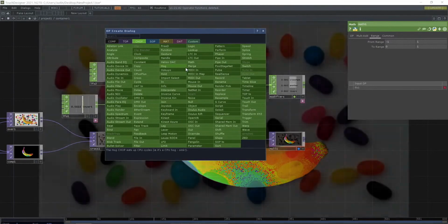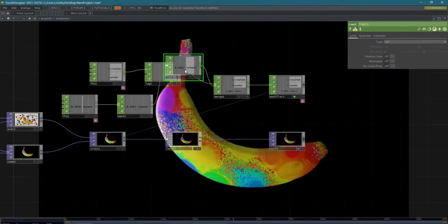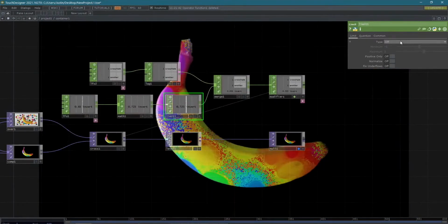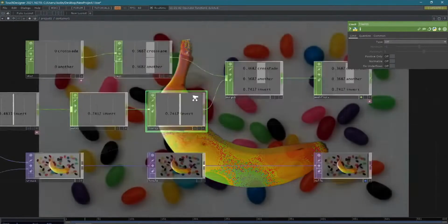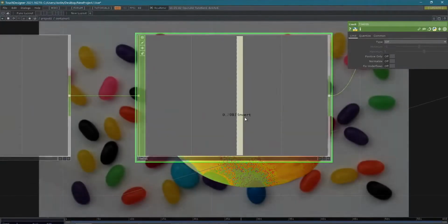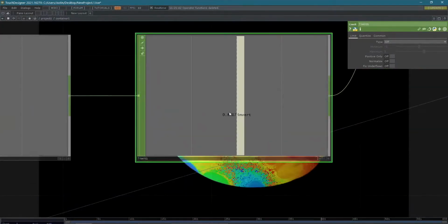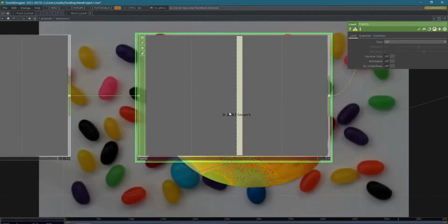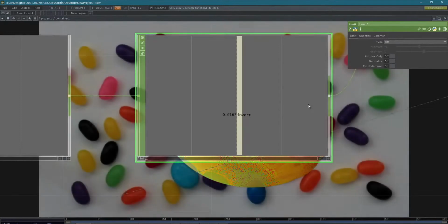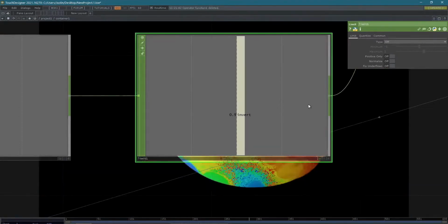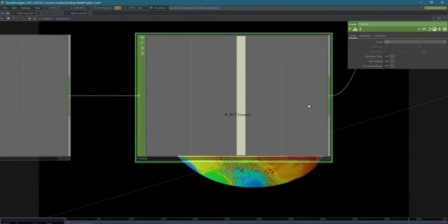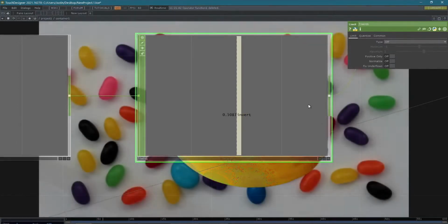It is limit. Limit is what we want. I was thinking clamp, but that's a different program. But what you can do, limit will keep you absolutely, like if we're looking at this now, we're seeing it's going a little over 1 because the input range is over what we told it. But let's say we want to strictly limit this to 1, because some things that you're dealing with, the built-in operators are pretty fault tolerant.